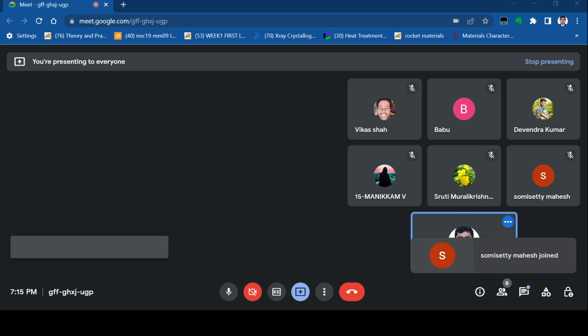From L we go this way, this is one path, then we come this way downwards, and again we go this way. So this is similar to going from here to here. We are taking this because, for a state function, it depends only on the initial and final position and doesn't depend on the path. So this type of question, when undercooling is involved, we have to solve like this. We cannot directly use this. This will give a wrong answer. So I'll draw that again in a new slide.